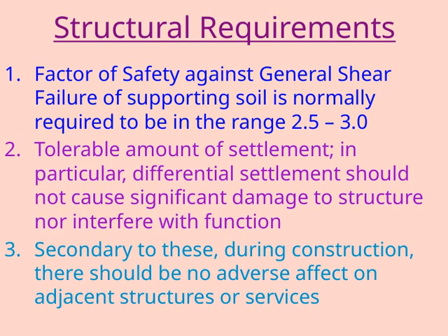Let's take a look at the structural requirements to ensure the stability and safety of our supporting soil. Typically, a factor of safety against general shear failure is required to be between 2.5 and 3. This means we need to have enough strength in the soil to withstand loads without risk of failure, providing a good margin of safety. Next, we need to consider settlement.